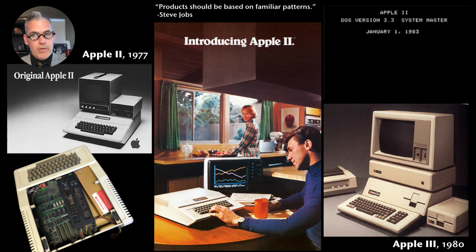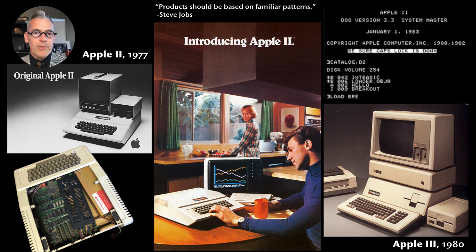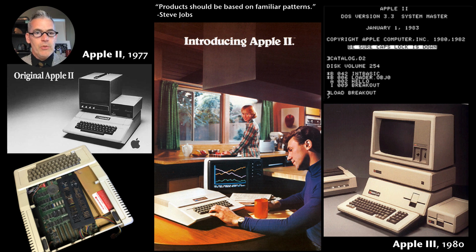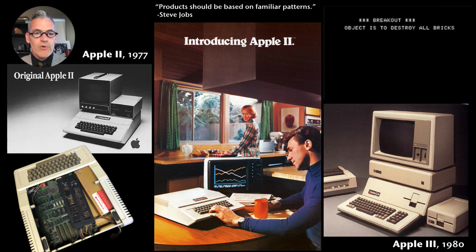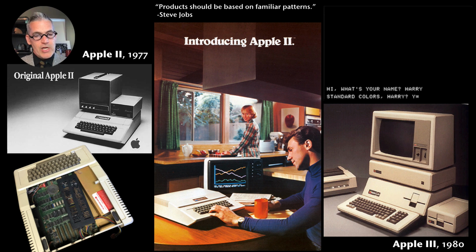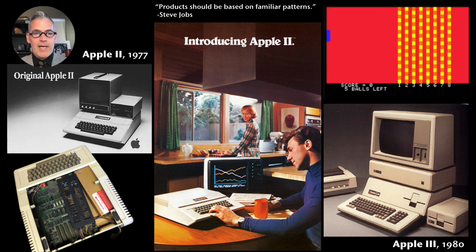The Apple II saw that technology housed in a way that really made it possible to imagine integrating it into daily life. The first plastic computer housings were made of what we call structural foam plastic. It's injection molded plastic, but at the last moment before the plastic goes in the mold, a gas is injected, creating bubbles. So the plastic skins over on the surface where it hits the mold, but it stays with a cellular structure inside.